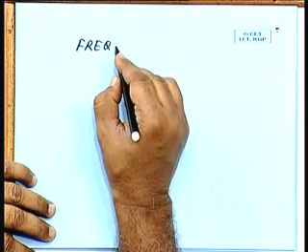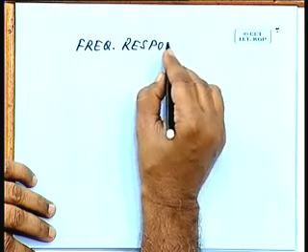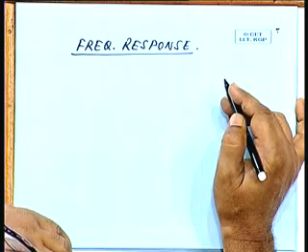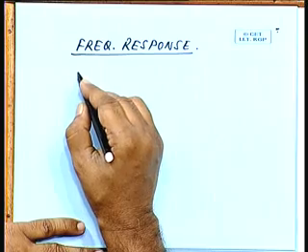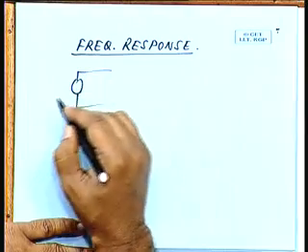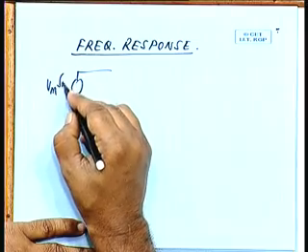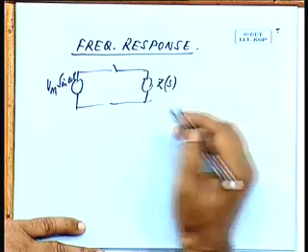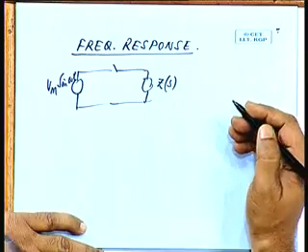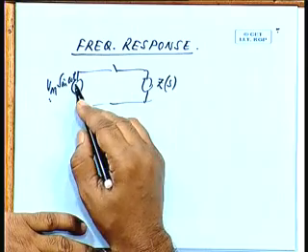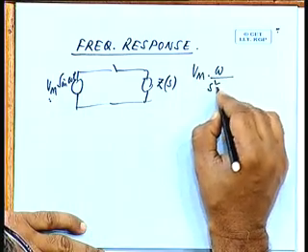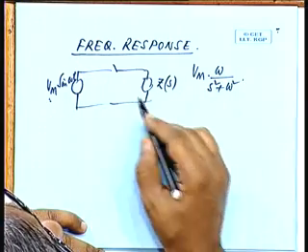Today, we shall be starting frequency response of systems. Frequency response of various types of networks. What do you mean by frequency response? When we excite a system by, say, a sinusoidal input Vm sin omega t applied to a network whose impedance function is Zs, all right, in the Laplace domain. In the time domain, we are applying a function Vm sin omega t. So, in the Laplace domain, this will appear as Vm into omega by s squared plus omega squared. So, this is our input function, Zs is the impedance function.